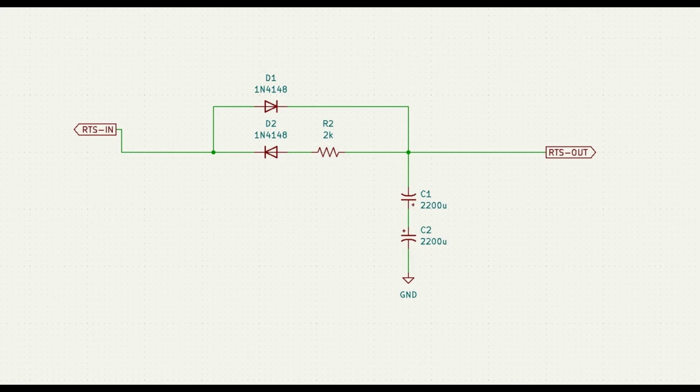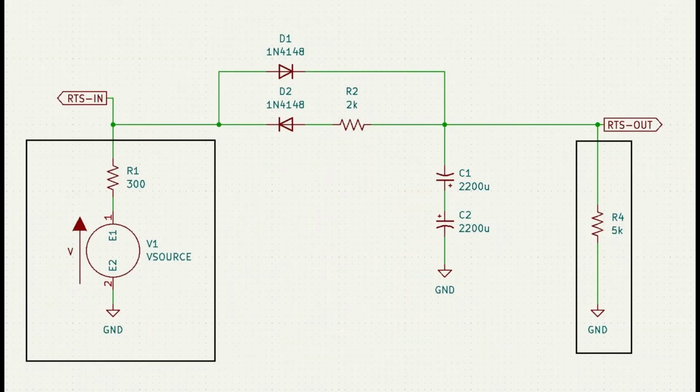And then this is a new attempt at playing with things in KiCad. As you can see, I laid the circuit out. But really, one of the many benefits of KiCad is you can do a SPICE simulation. So that's what we did. But in order to do a SPICE simulation, we had to add a few extra components.